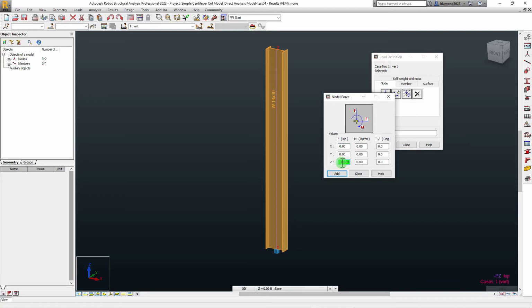Why 32.7? That's just because I've calibrated this structure. I know the failing load of this one particular section is 32.7, just to demonstrate the code check values and taking a structure essentially to its ultimate load as far as allowable is concerned. Alright, so we'll add this value.